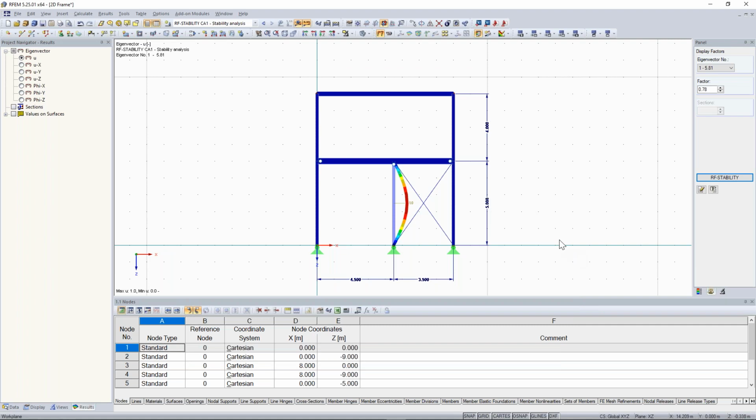Yeah, and maybe there's another question about getting slightly different results despite following the same steps and applying the same loads. Is there a reason for that? I mean, normally, if we have the same parameters, if we're following the exact same steps, and if you're using the default parameters of RFEM, we would all get the same results, but sometimes it depends on whether you're using theory of first order or second order, and those are parameters you might have changed. Maybe that would lead to slightly different results, right, Daniel? But other than that, I don't think we should be landing on different results.